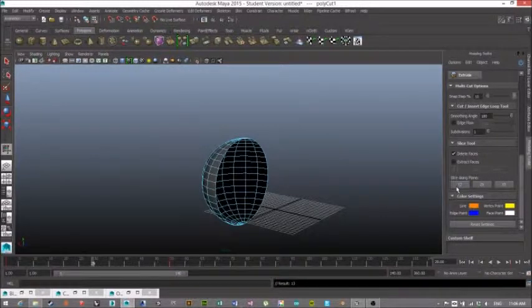Really, really important right off the top, though, if you're using Mental Ray, probably your best bet is the MIA material shader. It's actually developed by Mental Ray and Autodesk for architectural materials. So it's supposed to give you like the best looking copper and glass and stuff like that. You'll need to be using lighting with it, but they're already there. You just have to kind of find a bit of a way to navigate through the presets. You guys are all, when you're rendering, are you guys using like image-based lighting, or at least physical sun and sky? If not, start. That's like objective number 1 in your next free time, because it makes all the difference in the world for a render.